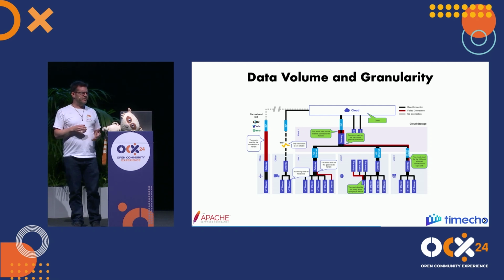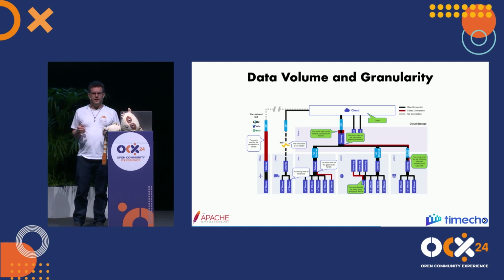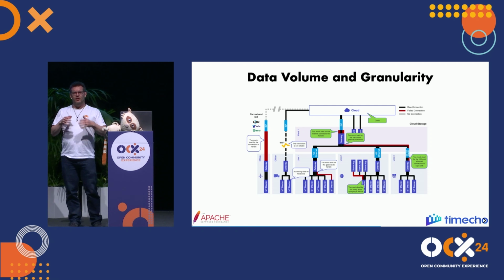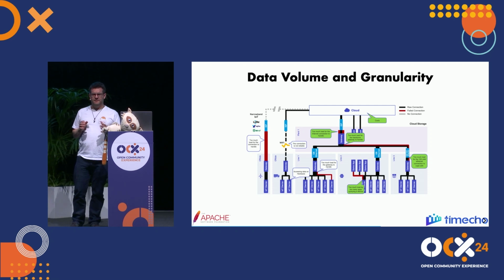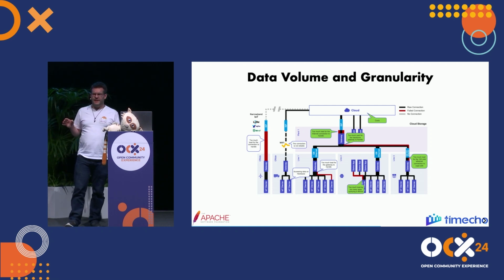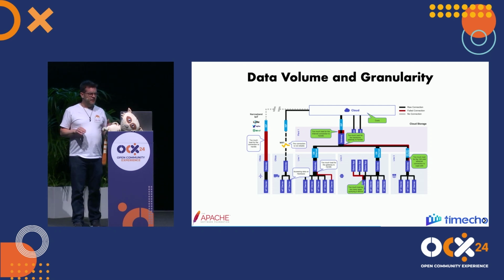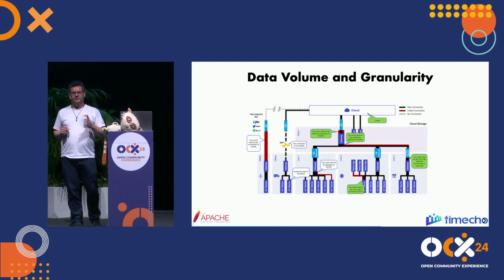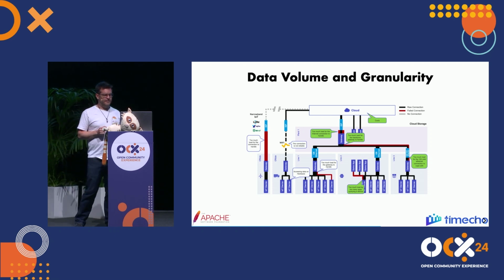And then there's another overall equipment efficiency calculator that also needs to query data from the PLC. So it's asking the PLC again. I've seen it quite often that the sheer amount of different clients asking the PLC the same questions makes the PLC shut down in the end. So in the end, your production line is flat, it's doing nothing, just because you've been asking the PLC too many questions, the same questions over and over again.